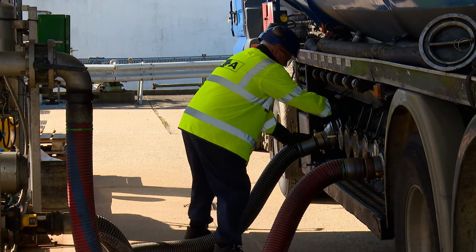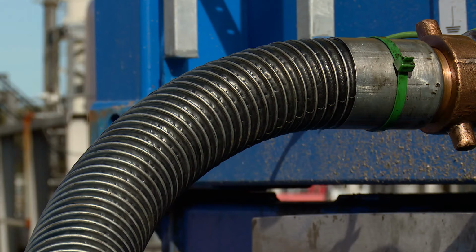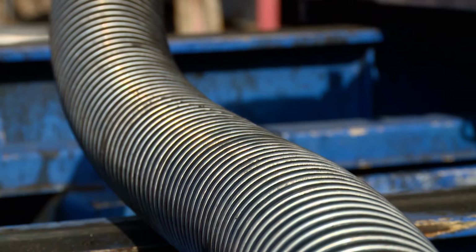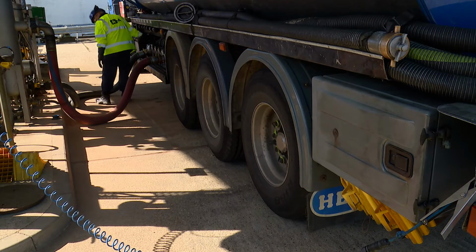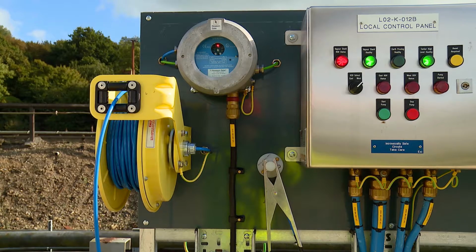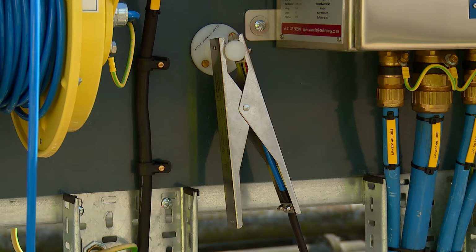Static discharges are a serious hazard wherever flammable solvents are transferred. To prevent static electricity accumulating and causing a spark, transfer rates are predetermined by the site, including relaxation times. Splash filling is avoided by bottom loading wherever possible, and earthing systems are in place to allow static electricity a safe route back to Earth.